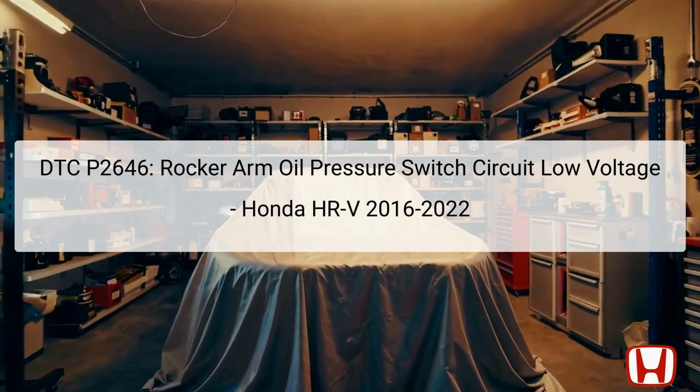The DTC P2646 indicates a malfunction in the rocker arm oil pressure switch circuit due to low voltage. This switch is crucial for the VTEC, variable valve timing and lift electronic control system, ensuring appropriate oil pressure transitions between different operating modes. Its location is typically near the engine cylinder head, connected to the engine's wiring harness.